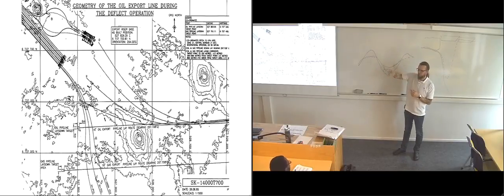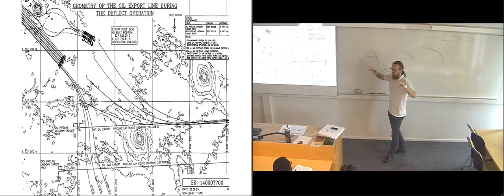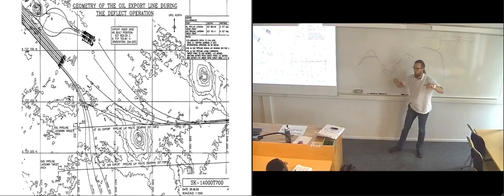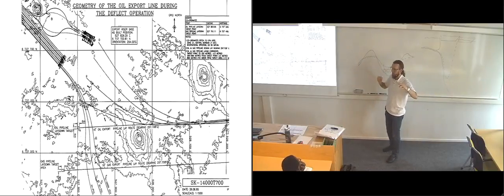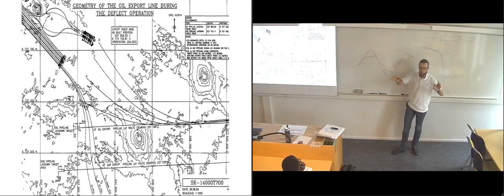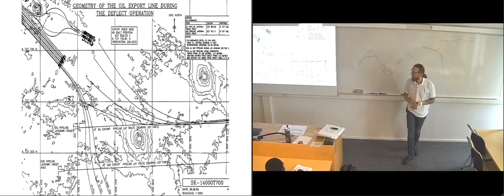If you put a chain around the middle of it and you lift it, you can actually see that it's sagging a bit. And that's within the elastic zone of the material. You could put it under pressure and push it even more into a curve without it being deformed, so that when you release the pressure, it would snap back. And if you lowered it down to the ground again, it would be completely straight.